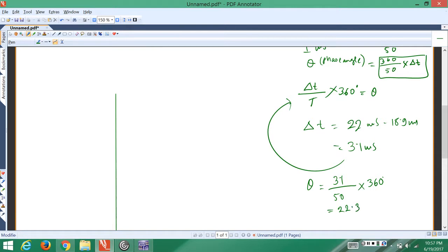If you perform a theoretical calculation of this phase angle for VR and VS, the voltage source or supply, you will see it would be something like 21.6. That's what you get if you calculate, and we are getting something like 22.3, which is slightly off, probably because of how we took the time reading using the cursors.